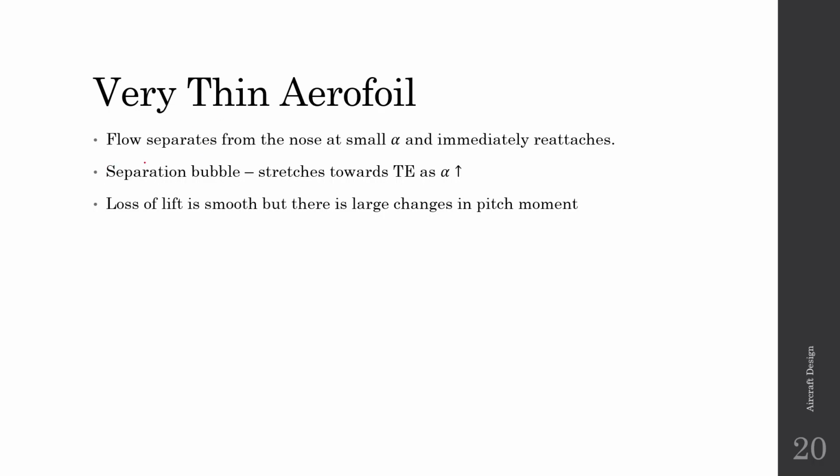And in very thin aerofoil, the same thing happens. So the first 2 points are same. The last point is different. So the loss of lift is smooth, but there is a large change in pitching moment. So this is the difference between your thin aerofoil and very thin aerofoil, that the loss of lift is smooth in case of very thin aerofoil.